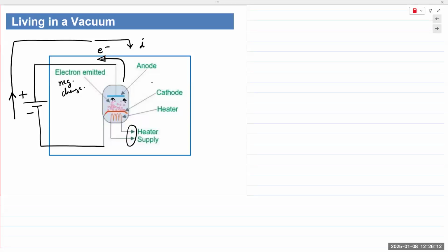And if you think back to chapter 1 of EE 201, a power supply is supplying energy. If an element is supplying energy, current for that element is always going from polarity minus to plus. For all other elements that are absorbing or receiving the energy, current will always go from plus to minus.